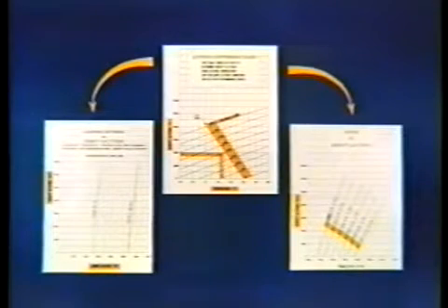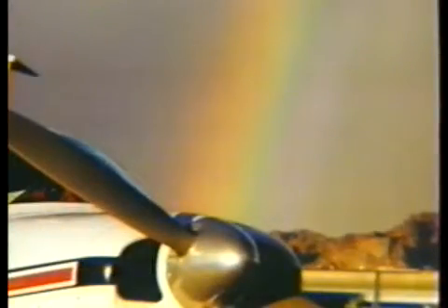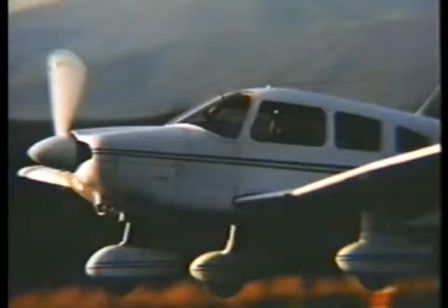Older aircraft publications use a two-step method that accomplished the same thing. These publications provide a means of using pressure altitude and temperature to calculate density altitude first, and then to determine its effect on aircraft and engine performance. To be technically accurate, humidity is also a factor in density altitude, but since its effects are minimal for landings, it is not normally considered. Density altitude doesn't have a whole lot of impact on landing rollout, the way it does on takeoff performance.